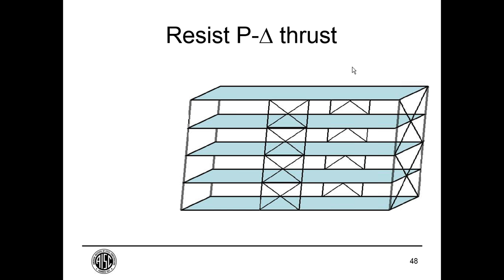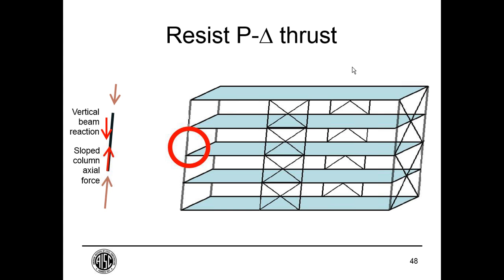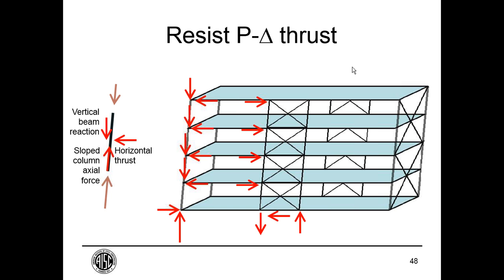When the building moves, as shown here, let's say under significant lateral load, the gravity forces that are delivered to this column, so here are the pass-through forces from the level above, just going down the column, but the gravity force that's delivered at that level, that's a vertical force. And that vertical force has to change direction to become a diagonal force in the direction of the column, which is now sloped due to the building drift. And that little change in direction creates a little horizontal thrust. And that happens at every level. So you look at that gravity column, and at every level, the vertical force needs a little bit of diagonal thrust in order to follow the diagonal line of the column. And that thrust works its way through the diaphragm and then gets delivered as an additional lateral load to our frame. So in addition to the lateral load that caused the displacement that's shown here, the P-delta thrust at every gravity column adds to our lateral load.